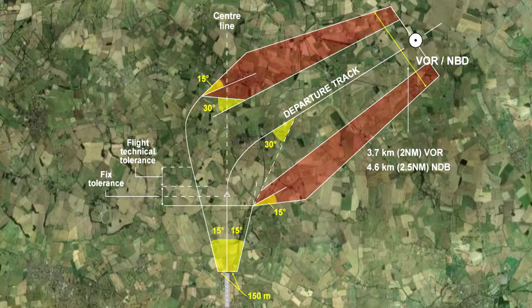You should note, especially for examination purposes, that 30 metres is approximately 100 feet. This fact will allow you to make sense of many of these difficult heights. For example, before metrication, straight flight was assumed to 400 feet above DER, and a minimum of 300 feet of obstruction clearance was guaranteed in the turning area.